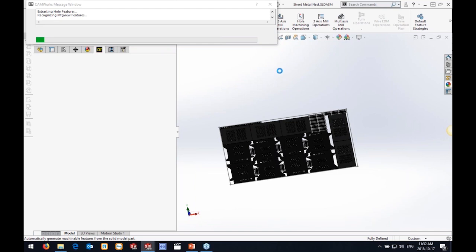But we also get that arc slowdown that I mentioned. So in your feed rate controls, if you're finding that you're rounding corners and things like that, what you can do is automatically slow your feed rates down in the corners, and you can control the angles and stuff like that it works to. It'll actually run down and slow down a little bit before the corner, and then go and change the corner at a low feed rate and pick back up again to the regular feeds.